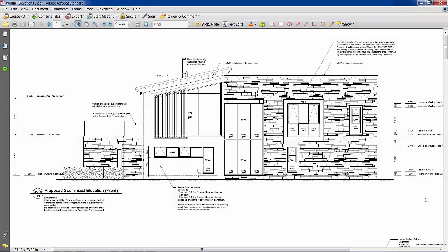This is just a third elevation to show a little bit more detail or a different option for some of the things that might be on the building. So in this particular case, the roof finish is zinc, and there's a roof detail relating to the zinc, which is a little bit different. The angle of the roof in this case is 12 degrees. And then the elevations have a number of different elements. So on this element here, we have sand cement, and that's clearly specified in that annotation there.